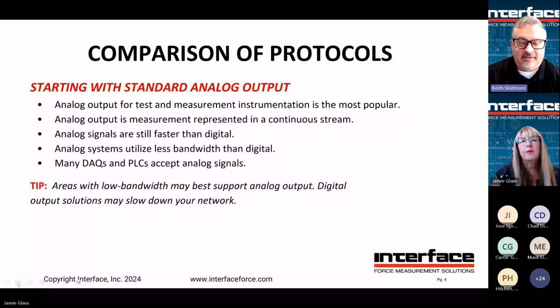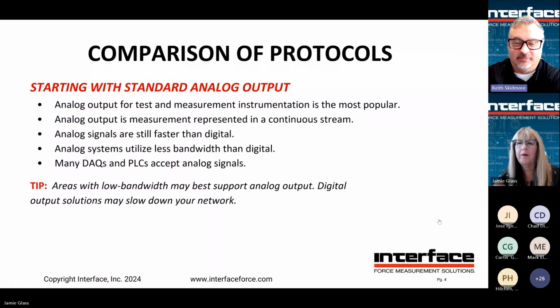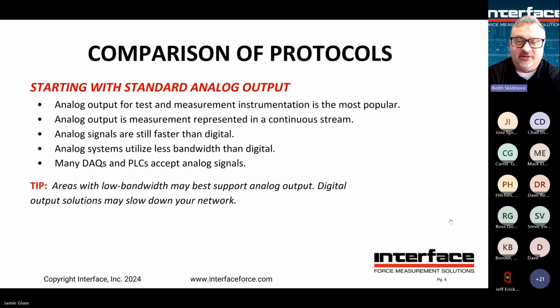Very typically, the signal from a load cell can be connected directly into some kind of data acquisition system, or with an inline signal conditioner or internal amplification in the load cell, the signal can be converted and amplified up to a higher level signal, like plus or minus 10 volts or 4 to 20 milliamps. Those signals then can be input into various systems: data acquisition, PLCs, controllers. That is still by far the most common method used today.